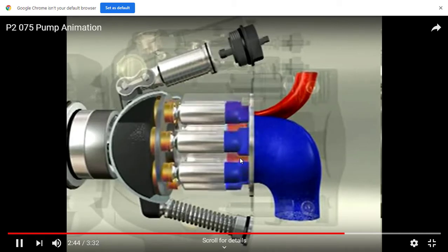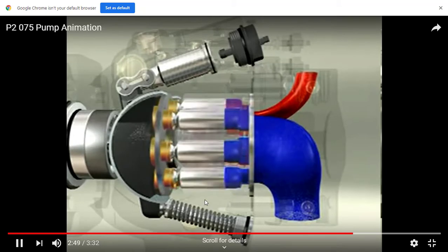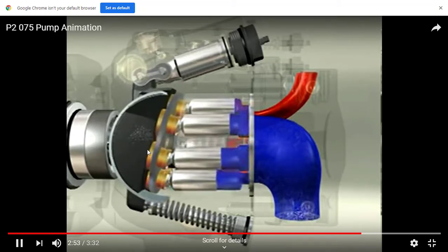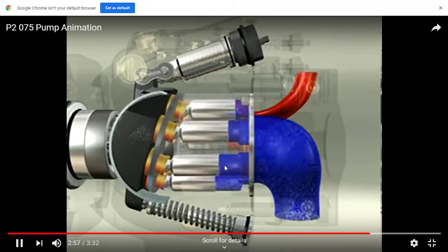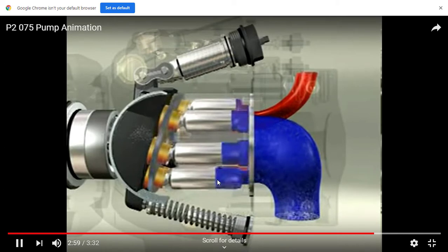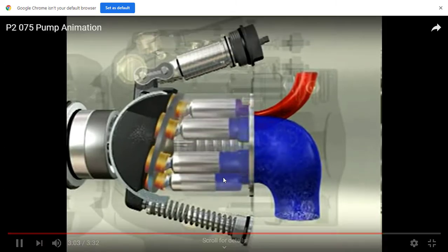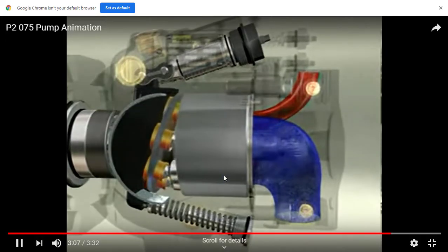In fact, you can completely stop flow if you make the swash plate go completely perpendicular to the pistons. Then it'll just sit and spin. But when we angle that swash plate, fluid flow starts again. So we're going to work with the bore and stroke of each of these pistons, and that's no different than the pistons that you would see inside the cylinder of an engine, except they're a whole lot smaller.